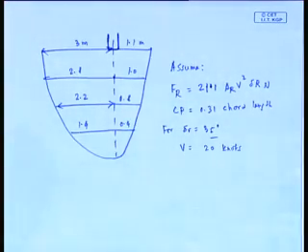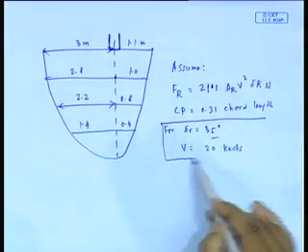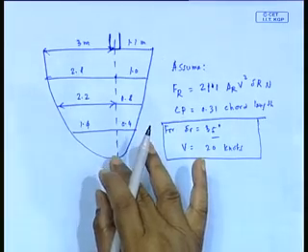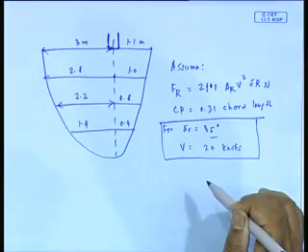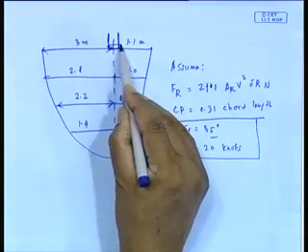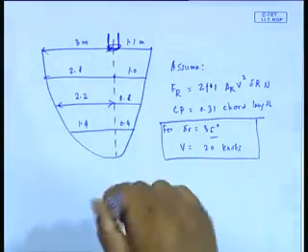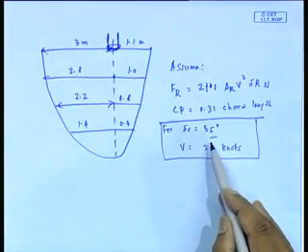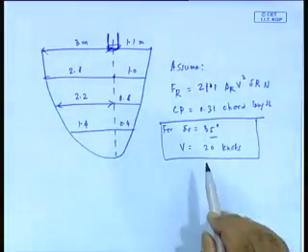The problem was something like that. The problem says that there is a rudder, a simple problem of this type. This is not uncommon for small boats, country boat type of thing. Find out what will be the bending stress coming on that point. At this point, because it is a supported rudder, you are supporting it here, obviously you want to find out how much stress is coming. Speed is 20 knots, and the rudder can go up to 35 degrees. So obviously the maximum force will come at 35 degrees.